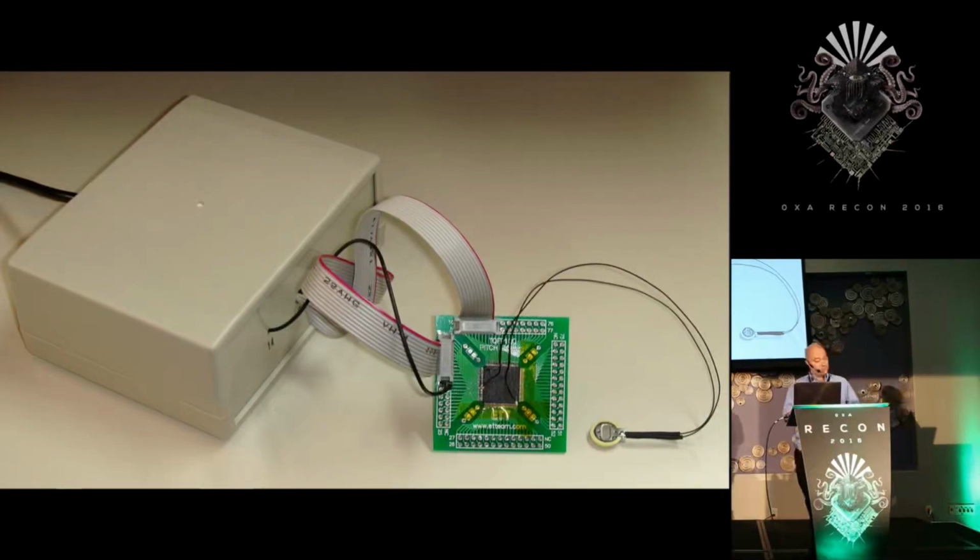So now I have it hooked up to my glitcher, which is now inside of a box. It looks much nicer. And I can now start to glitch the chip with the battery on it, so the RAM is valid. When I started to glitch, I found that my timing had changed, so I wasn't really sure if this was due to some different oscillator settings or if there's a different code path because the other chips had wiped RAM. But anyways, by modifying the time of my glitch, I was able to get the same glitch to work, and then I was able to execute my code on the chip with the valid RAM.